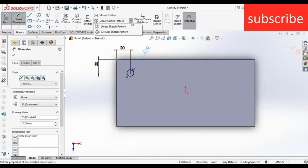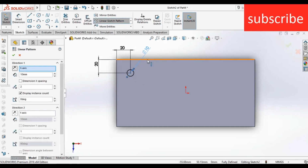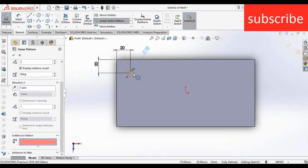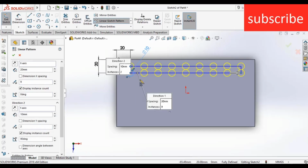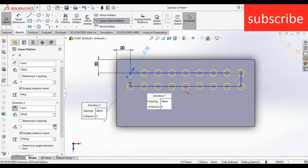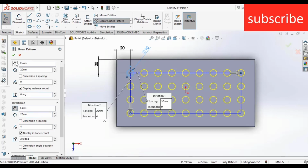Now go to linear sketch, select linear sketch pattern. After that go downwards, select entities to pattern, select this sketch. Make sure the distance is 20 mm and increase the number of the pattern. Now select the y-axis and just increase the pattern. As you can see, they are coinciding, so make sure you increase the center distance between them. So increase it and click on this reverse direction. After that increase the number as per your requirement.